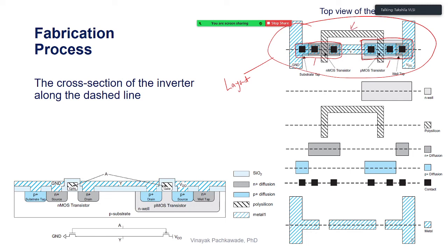For instance, you will draw the poly, you will have the output Y. You see, the source and drains are connected, so this is the output of the CMOS inverter. Then you will draw the metal here to establish the ground connection, and the metal here to establish the VDD connection. That's it. Even the body will be tied. The body of the NMOS will be shorted ready-made, and the body of the PMOS will be shorted ready-made, and you only need to draw metal and poly. So nowadays there are many facilities in advanced computer software that help the designer shorten the turnaround time, the chip design time.